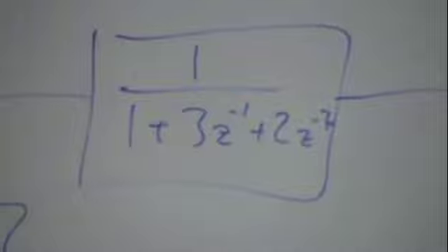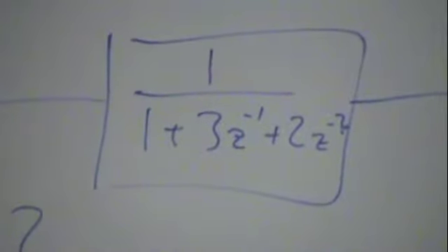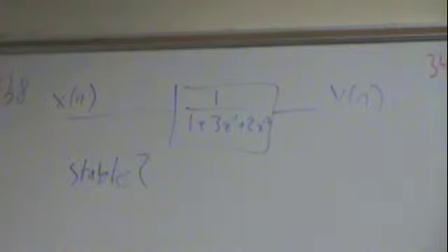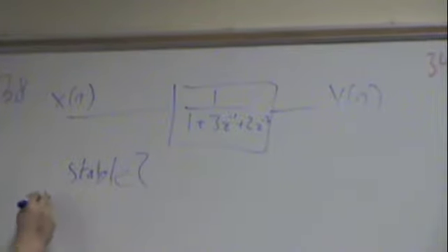So, does anybody remember what tells if a filter is stable or not? John, do you remember? Nope. Okay, poles are on the left-hand side. That's absolutely right. For analog signals, for x of t or x of s, for Laplace transforms, if the poles are on this side of the equation, it is stable.